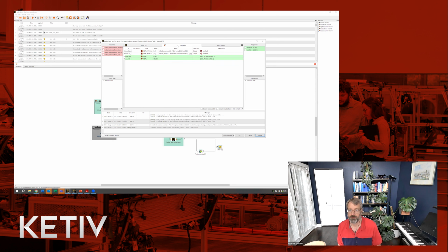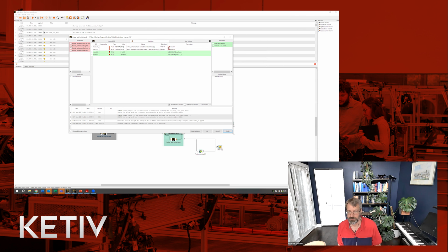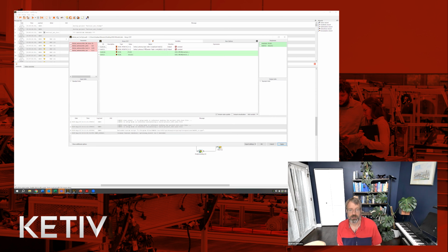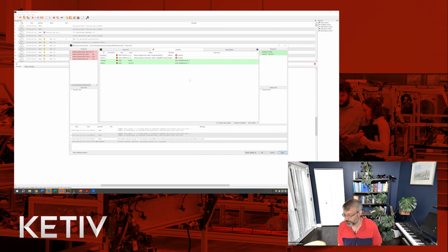And then if you go to the variable tab here, typically those table variables, you'll notice, are in this format of real XY data 1-to-1. And so it's an XY table format. And when we're running in Optislang, we want to have our variables be a real or a single valued variable.